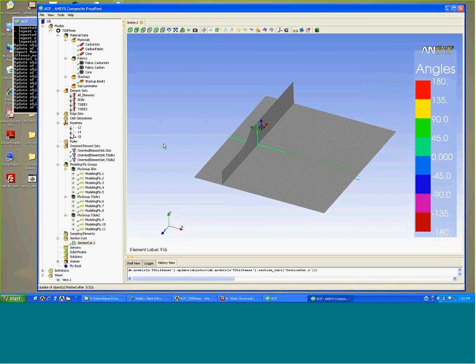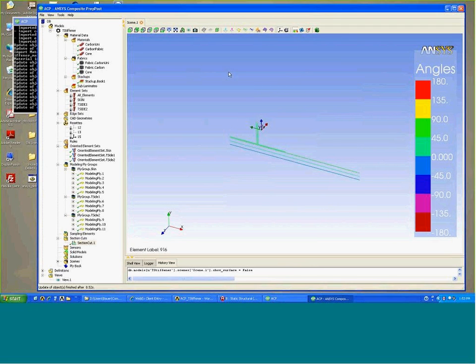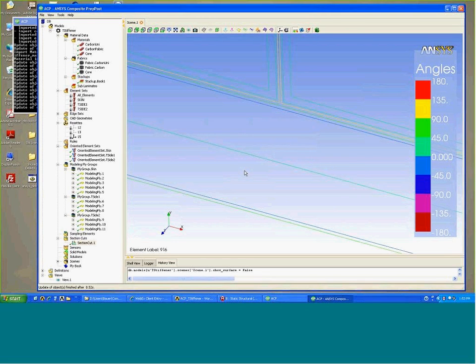So this allows us to verify the final composition of the laminate definition. Let's turn off a couple of visualizations. Let's turn off the shaded surface and the element edges so we can zoom in here to verify our stacking sequence. So here we can see, for the section cut, we have the 2 skin plies. We have a core ply that's fairly thicker, and then we can see our L, our angle definition.